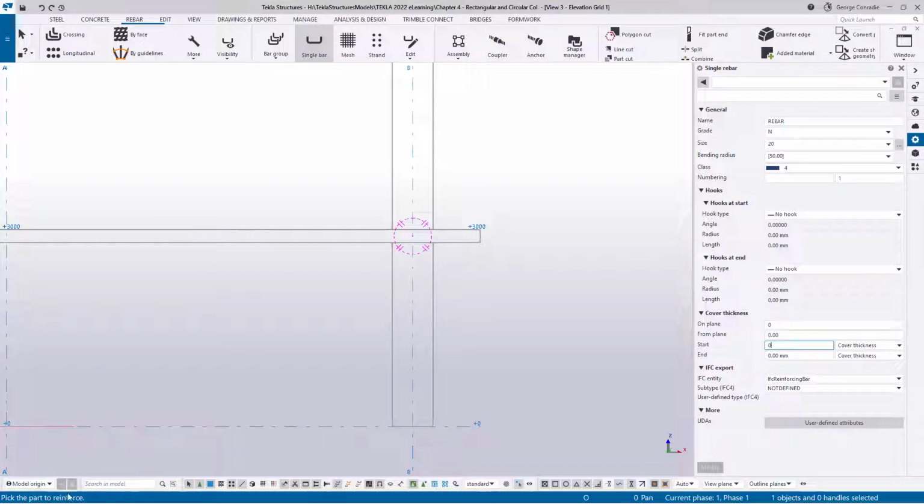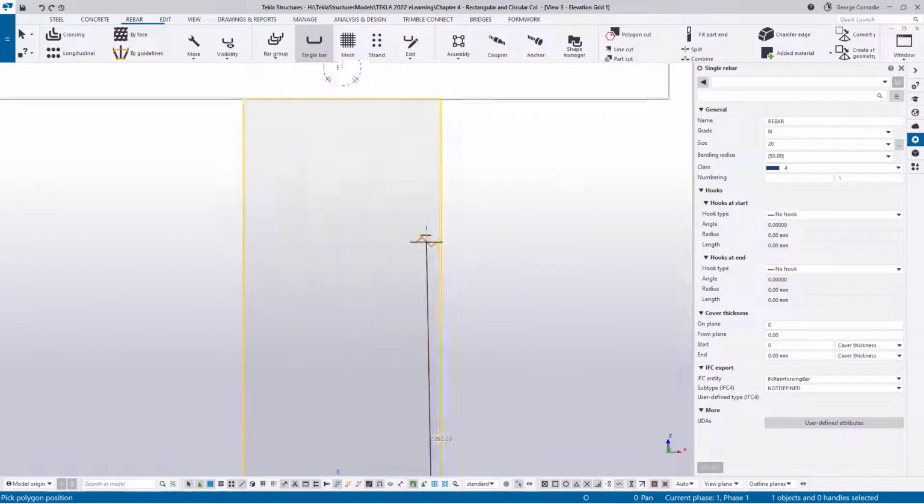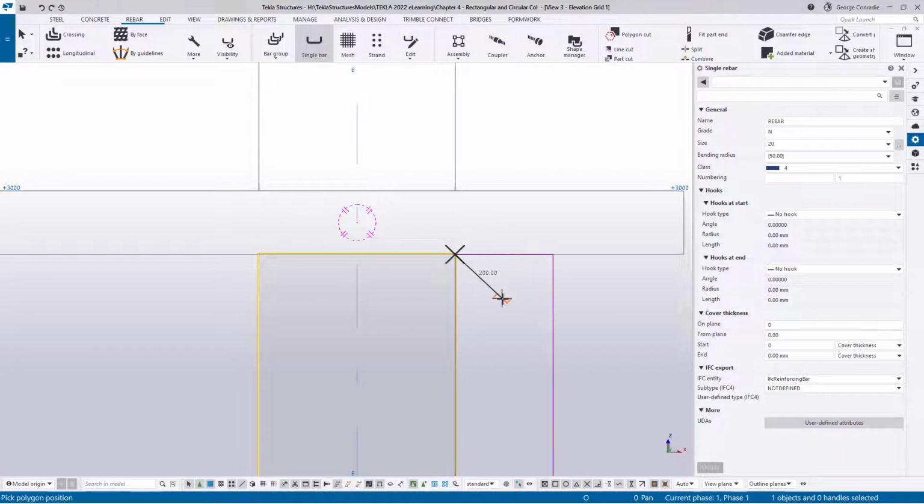So the first thing that Tekla is asking is pick the part. So what we're going to do is pick that part we want to reinforce, and then the shape. So we need to do a joggle bar or a J bar or a crank bar, as it's known. We'll start at the bottom there, right on the edge, and go up to the top of the column, then to the soffit of the slab, top of the column, then the start of the next column, top of the slab, and I'll just keep them straight now.